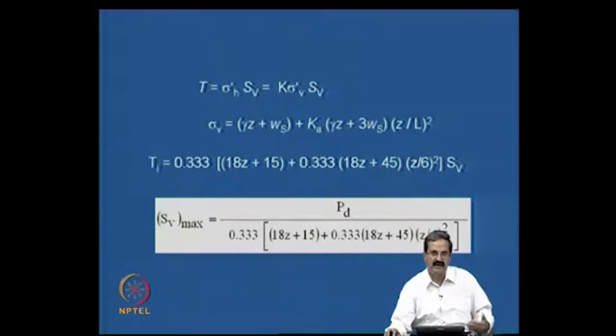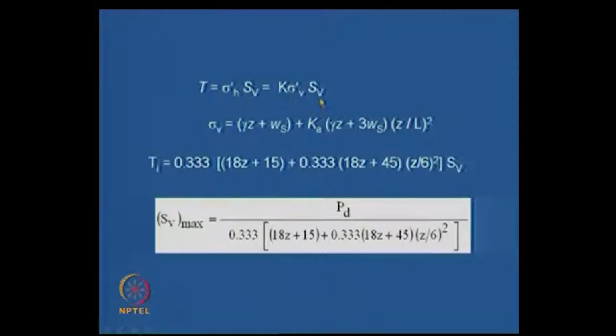Now, the internal stability, when you are trying to deal with that, we should calculate in terms of the tensile force, and this tensile force is given in this expression in terms of the vertical spacing, because the geogrids horizontally you consider as 1 meter length. Based on this, you can get an expression for Ti, the reinforcement force required at any section, at the i-th level.